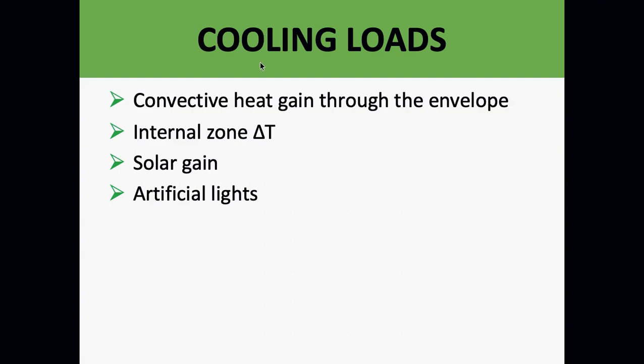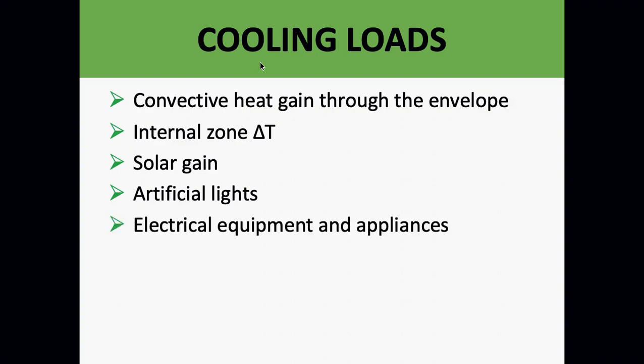Okay, ballasts give off the most heat. And then LED lights, by far, are more efficient, not only with power usage, but with heat generation. So there are some benefits here, and the power companies are starting to give a lot of rebates on this. But take it into account. If I suddenly have an office space that has always had a lot of fluorescent lights, look around any commercial building ceiling if you have the drop ceiling, and all of a sudden they start replacing all of those lights with LED lights, which is actually a project going on in a lot of areas, what's that going to do to my cooling needs?